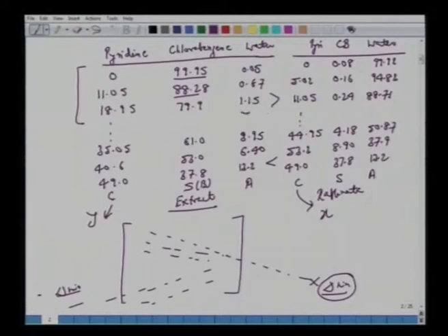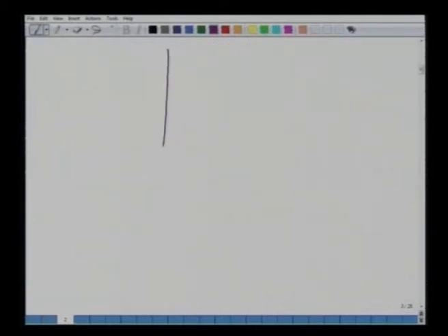So again, based on these data, one has to plot. Let's see that again, we use this rectangular system. So here we have 0, B 100%. Essentially we are plotting the percentage amount of solvent. So instead of a triangular diagram, now we are plotting this using rectangular coordinates, with X and Y here, and we have the percentage amount of solvent. Now again, we don't have to plot all the concentrations. Maximum maybe we have 60 here. So C is 60%.